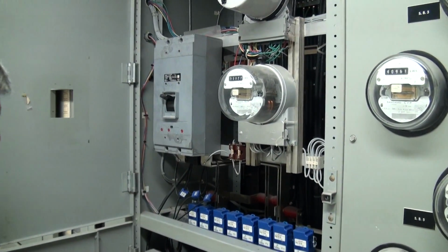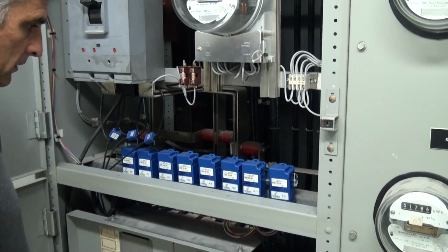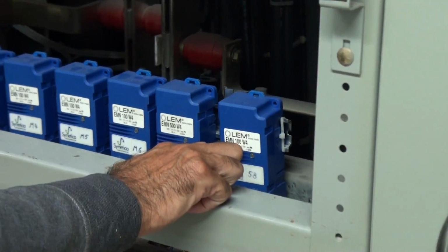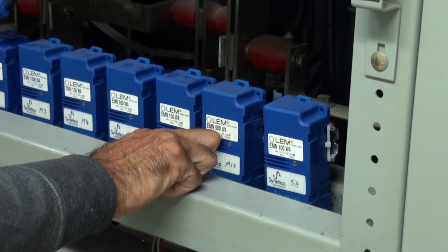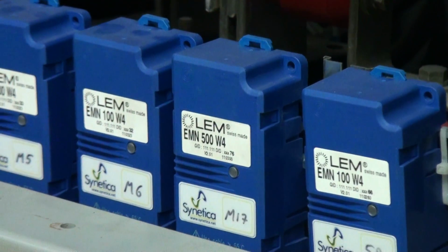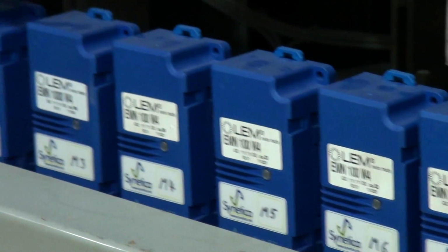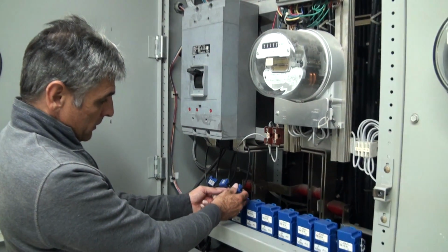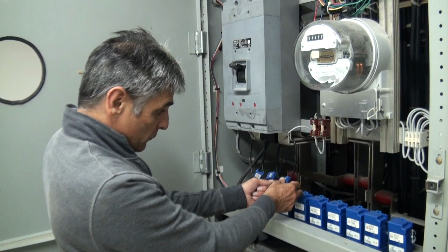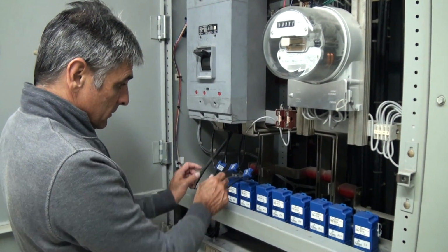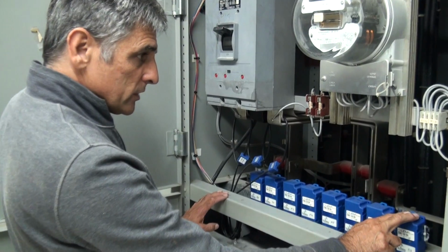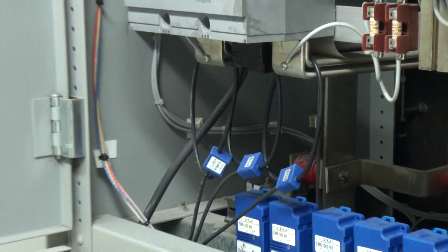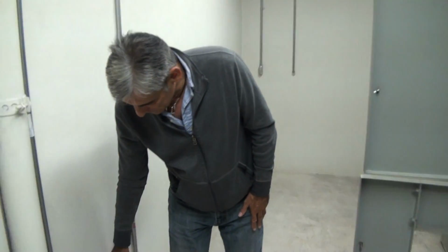And these are the wireless meters. Each unit is different values. This is 100 amp, 4 wire, 500 amp, 4 wire, and so forth, 1000 amp, 4 wire, etc. Basically, it's a Rogowski coil, and we just clip the coil around, connect a 3-phase supply to each one of these, and that is wirelessly streaming to a repeater.